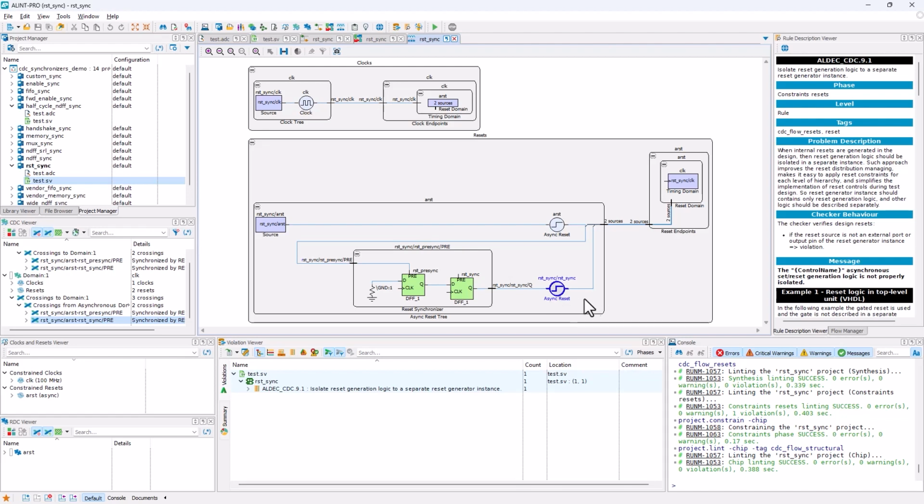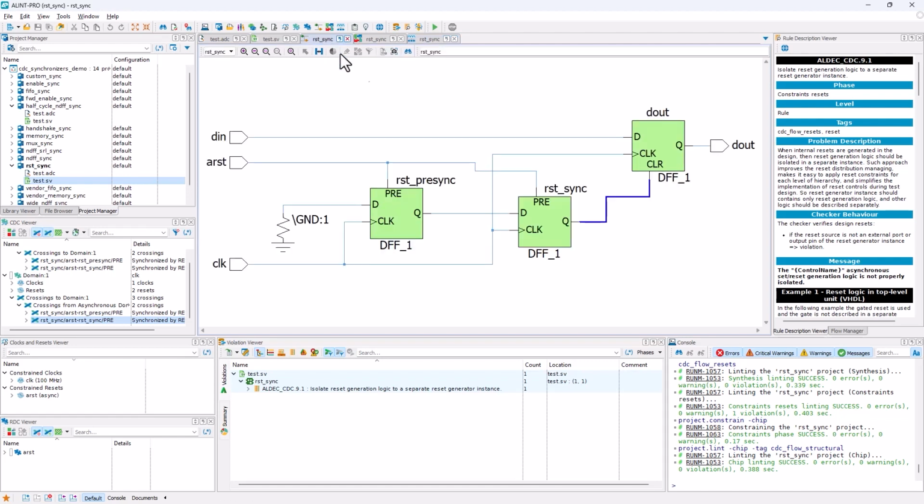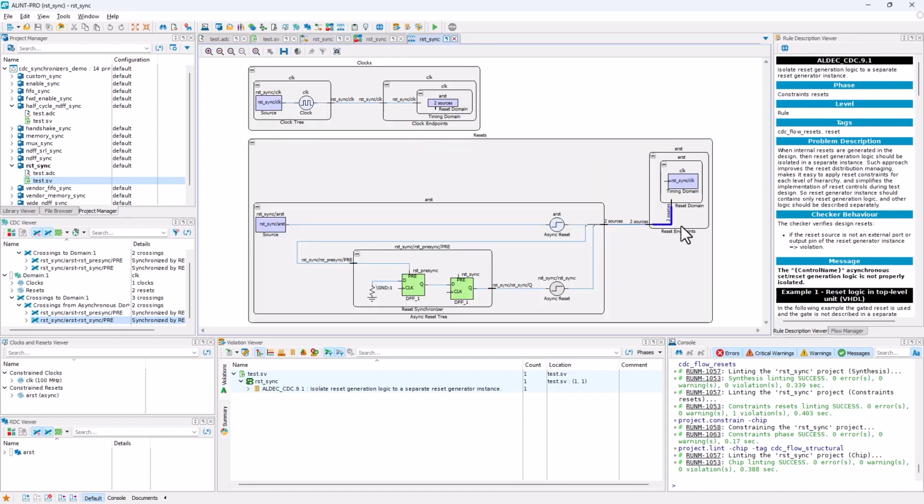We've just made sure that its deassertions do not line up at the same time as the assertions of our clock. But it's still asynchronous, and so we feed this signal as well as the original asynchronous reset over to whatever modules they're going to. In this case, we know what they are. It's just going to be the resets for these two and the reset for this register here. And so that's why it lists those two sources.